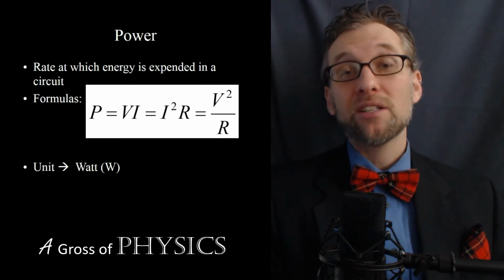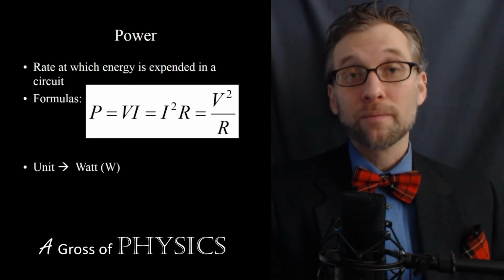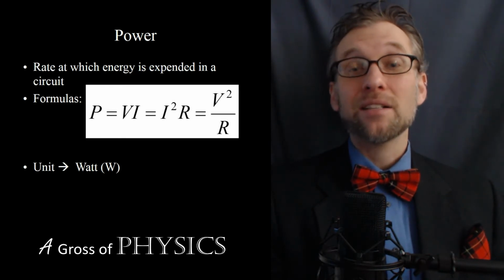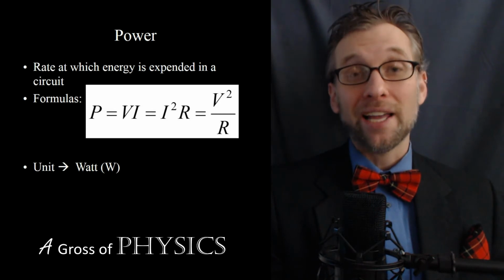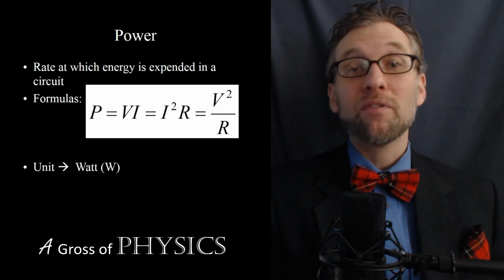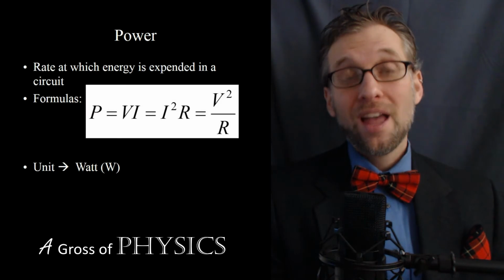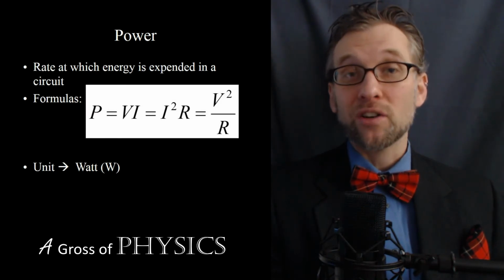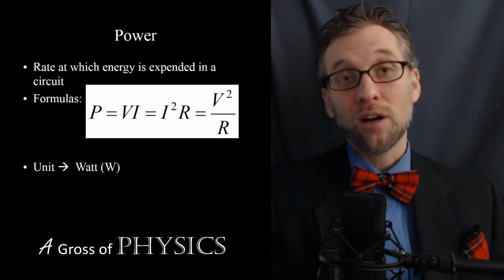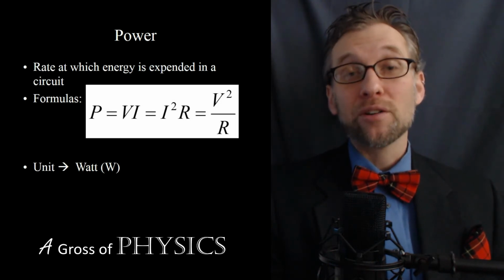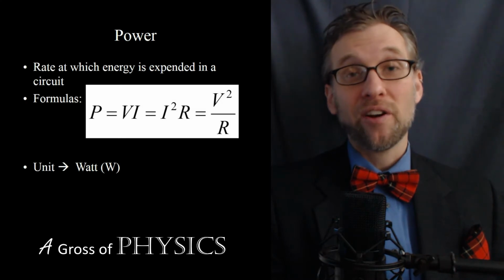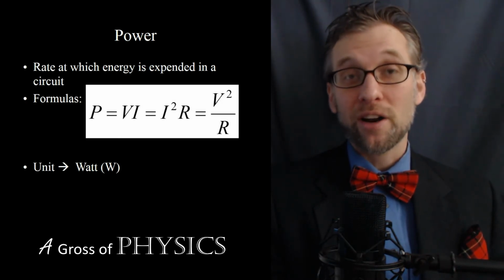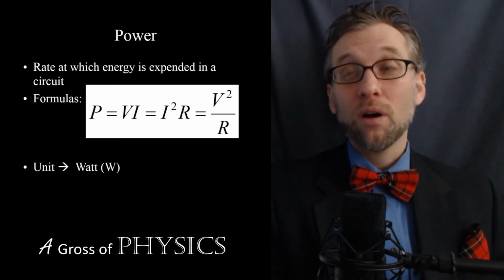And if you have very low resistance, that's going to increase the current. Remember, the wall outlet provides 120 volts of push. If you have a really low R with V equals IR, that's going to provide a very large I. So if you short the circuit out, it provides a huge current flow. If you don't have a circuit breaker or a fuse box in your house, it will allow too much current to flow, and you could actually melt the wires in your wall and possibly burn down your house. Your insulation will catch on fire after the insulation on the wire melts, and then you'll start a fire in the wall.